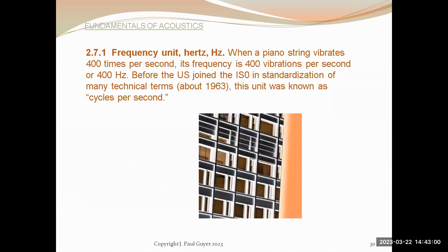The amplitude of its vibrations, up and down, increases until, if you continue applying that forcing frequency at or near the resonant frequency of the system, pretty soon the amplitude of oscillation gets so high that the system breaks.